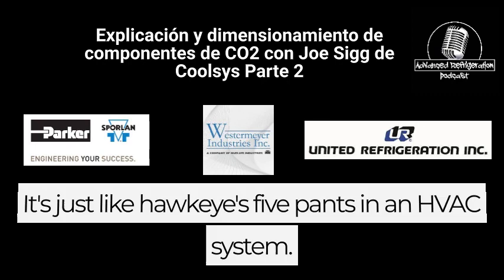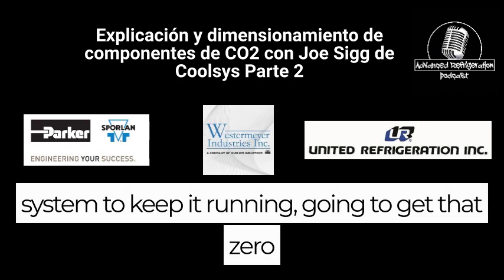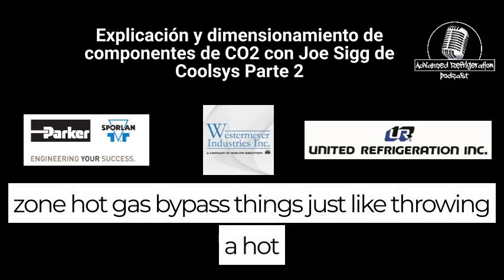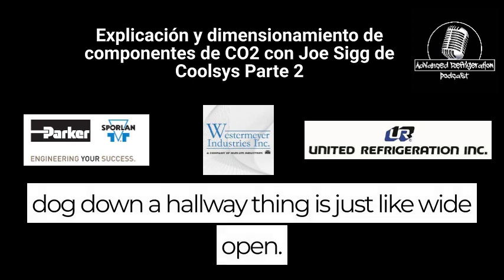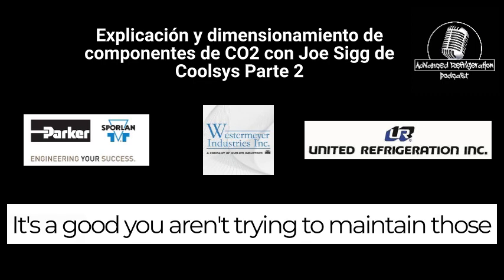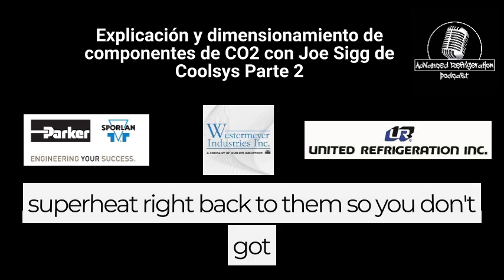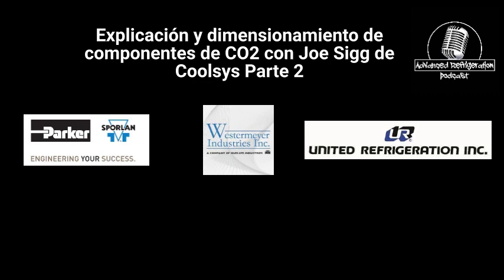It's just like hot gas bypass in an HVAC system, right? It's the same idea. You're keeping some load on the system to keep it running. You get that zero zone hot gas bypass valve, and the thing is just wide open. You're trying to maintain those compressors, keep that load on, and it'll add that superheat right back to them, so you don't have to worry about liquid flood back.